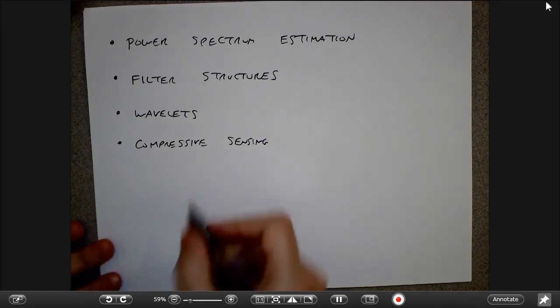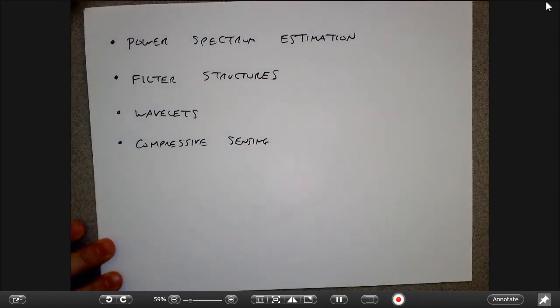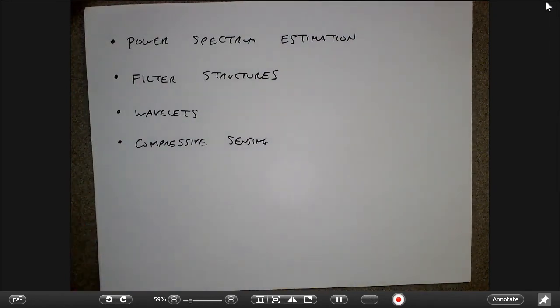There's a whole world of analysis of what's called compressive sensing that's kind of cool. And those kinds of techniques allow some very sophisticated systems. So for example, instead of taking an image of a scene or taking a radar reading that has like 100,000 elements, I can randomly send out projections into the world and only get a few signal responses back, and that allows me to reconstruct the original signal without having all the information that we might need according to the Nyquist rate, for example. So this is a way of circumventing the Nyquist rate in some sense for certain kinds of signals, which is really kind of neat.